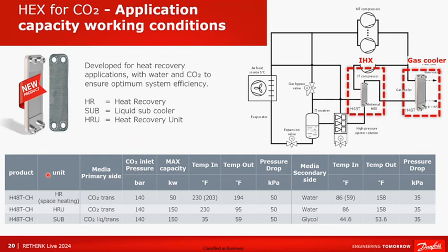Why heat exchangers are so important? Well, you saw the example of how sensitive is the COP of all heat pumps, depending on your approach in the heat exchanger and on your superheat control. Well, heat exchanger is very important. Plate heat exchangers are the most efficient heat transfer technology. It is also lighter heat exchanger and obviously with a lower footprint than, for example, tubular heat exchangers. So there where applicable, this is a more energy efficient solution.